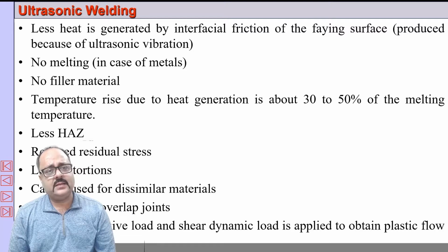particularly in the case of metal ultrasonic welding. In plastic ultrasonic welding, a slight amount of melting can take place, but in metal ultrasonic welding no melting takes place, and therefore the welding is carried out in solid state. Therefore it is called a solid state welding.